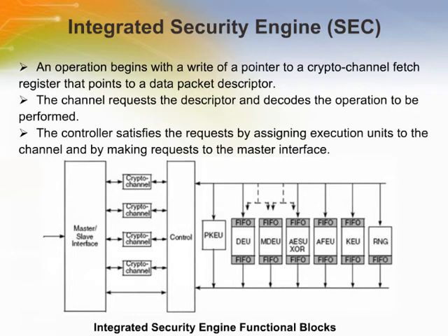A block diagram of the integrated security engine's internal architecture is shown. The SEC is a modular and scalable security core optimized to process all the algorithms associated with IPsec, IKE, WTLS or WAP, SSL or TLS, and 3GPP. It is not a protocol processor. The SEC is designed to perform multi-algorithm operations in a single pass of the data. The bus interface module is designed to transfer 64-bit words between the internal bus and any register inside the SEC.